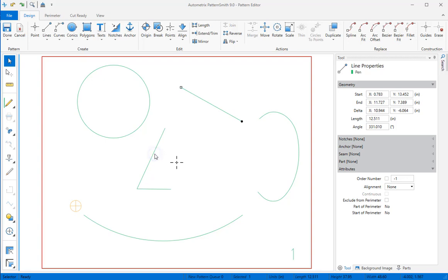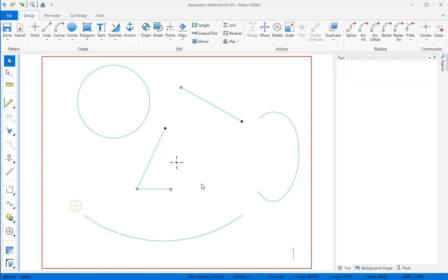We just showed snapping a handle. You can also snap an entire element or a selection. I'll make a selection and then press the Control key before I click on a handle. Now my selection is following this handle. Still holding the Control key, I'll release the mouse when I'm within range of the point I want to snap to.